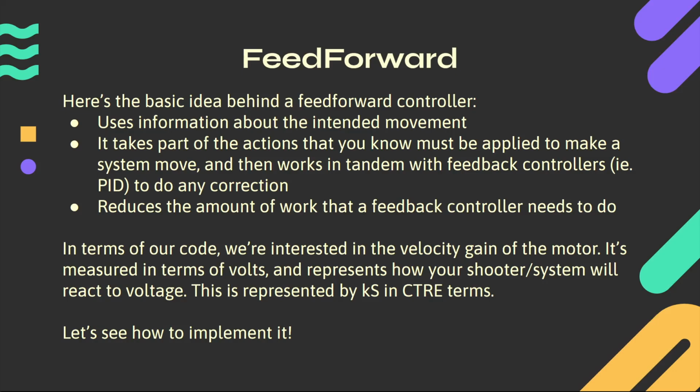Because we're reducing the amount of work that the PID controller has to do in the first place, it is a faster way of getting to your desired position. It is very much possible that you could only have a feed forward loop and never use a feedback controller at all, depending on the type of mechanism and the constraints that you have.